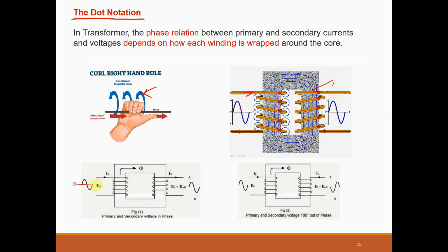So we have here an AC input. The current direction is from left to right, right? Here is also current direction are the same. They are said to be in same polarity. Okay? And here, this is an example of opposite polarity. Look at the winding here. It's entered from this side, right? This winding. And look at the other winding. The winding is entered from the other side. So it will have reverse.